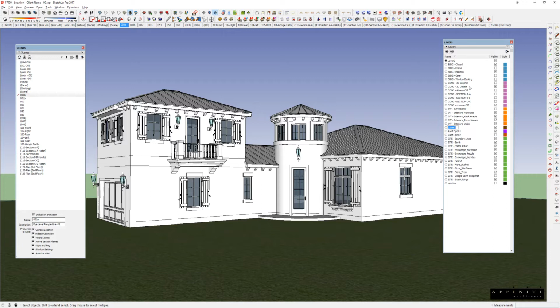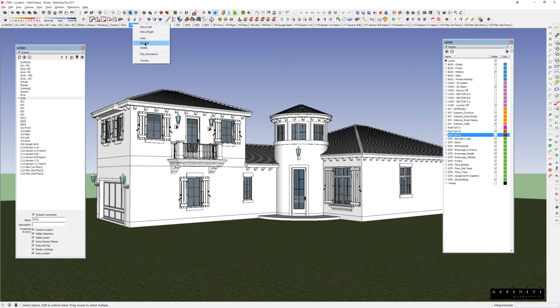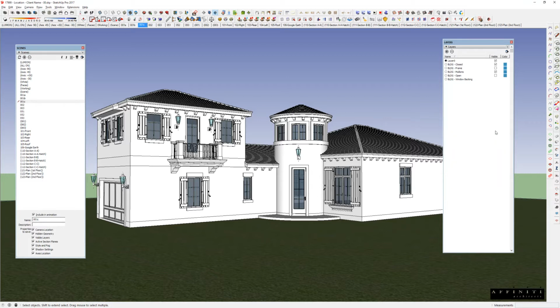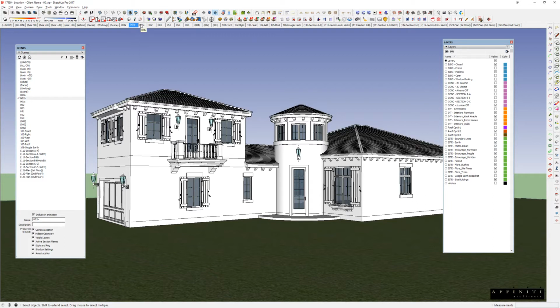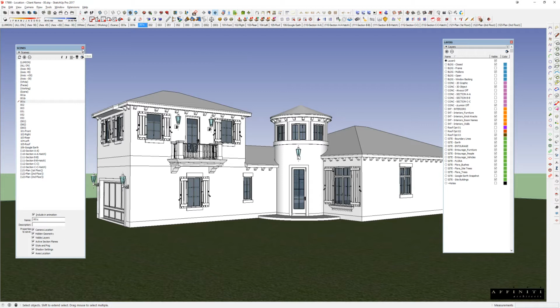I'm actually going to add one more, because we're actually going to build one more three-dimensional roof real quick. Option 3. And so I'm going to turn option 3 off in A, update, go to B, I'm going to turn option 3 off in B, update, and I'm going to add one more. I call this one 001C, and put on option 3, even though we don't have an option 3 yet, but it's pre-built for it.